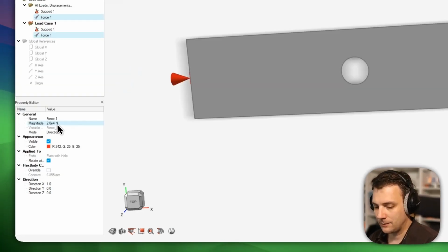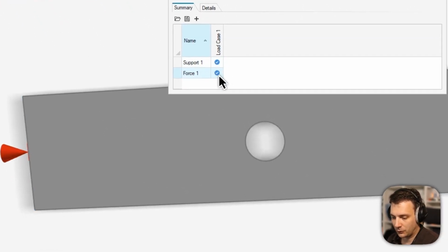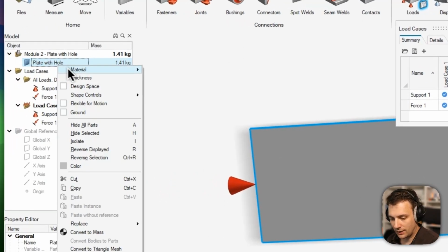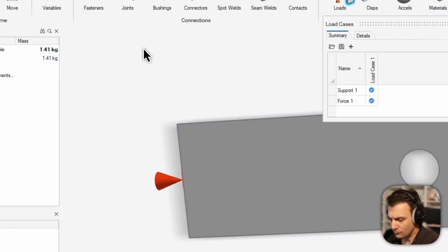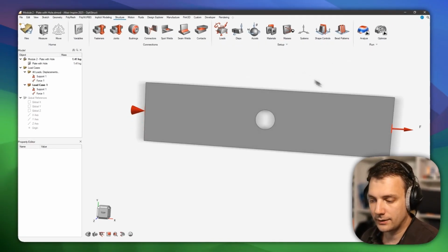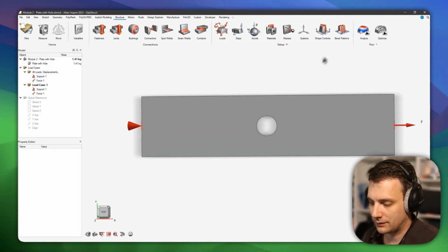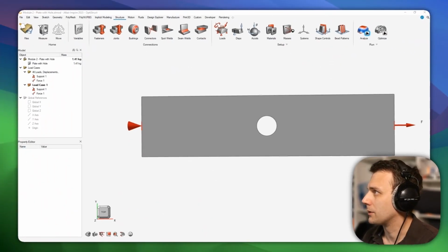But basically, you see it's just one load case with the set constraints. You have the support, the force. You could check the material. That should be default steel. And that's that. So you could, without further ado, just run it and see. I did do a couple of tests, but let's just run it for once so that you see how it's done.